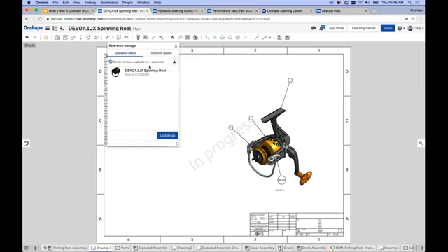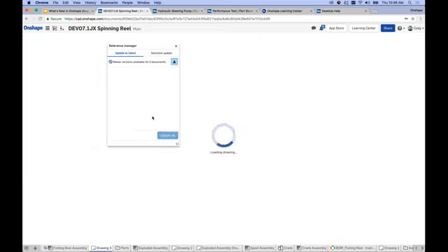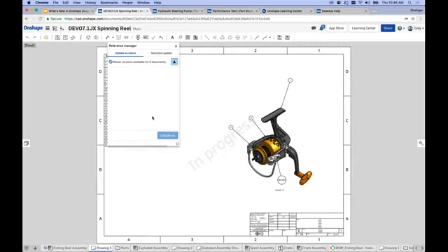How do I insert that revision into a drawing? And the short answer is you can insert it initially, as I showed you, by clicking that filter, or you can take an existing drawing or insert the active and decide to change it later just by right-clicking the tab and choosing change to version. And what you'll see is this change to revision, where I can change from the active workspace to a revision, right? Hit update all, and it's going to go through and update the drawing based on that revision. So it's essentially taking that active workspace and swapping it with the revision.